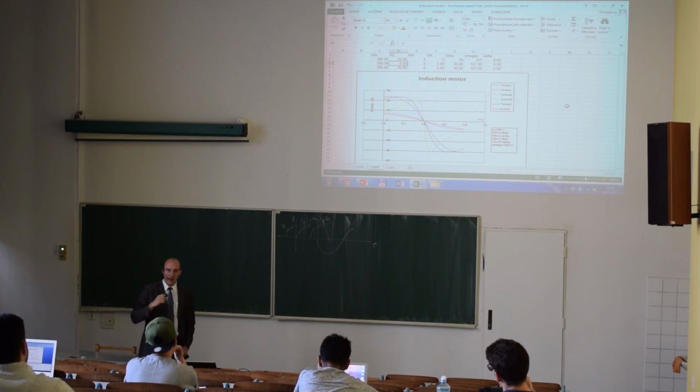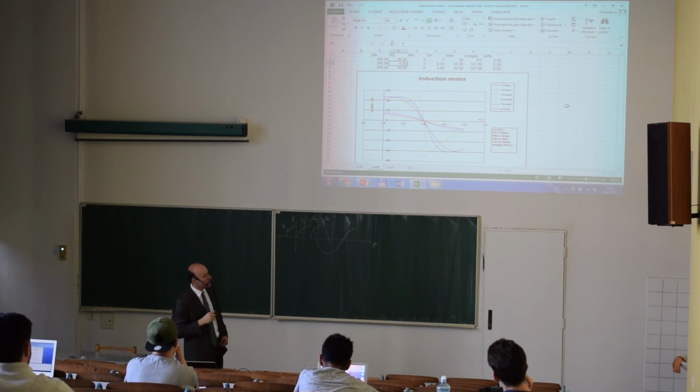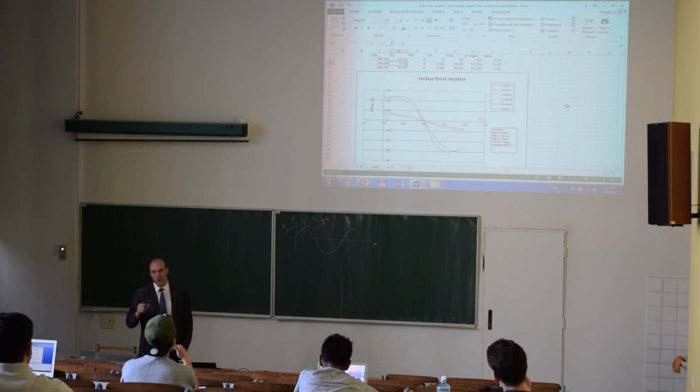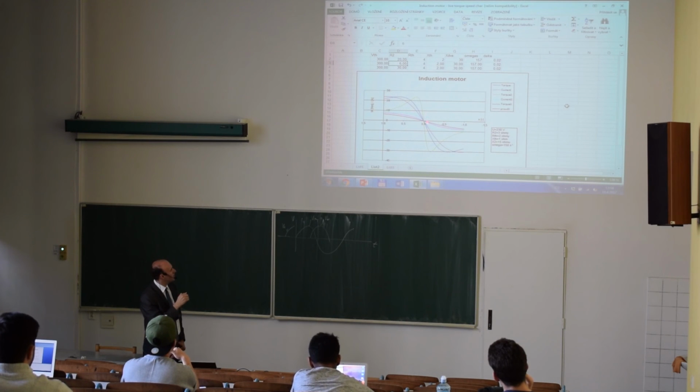So there's a very big advantage of the wound rotor, that we can change the torque speed characteristic by changing the value of resistance in the rotor.